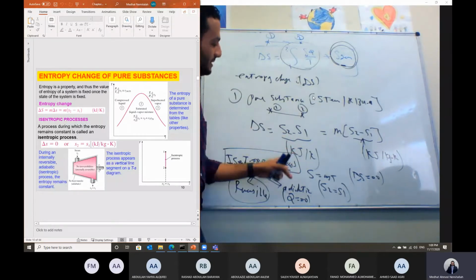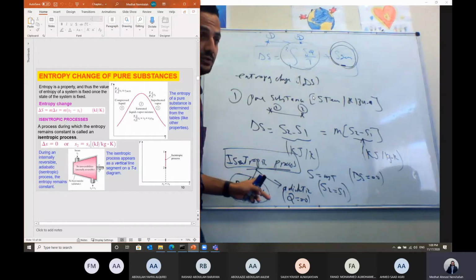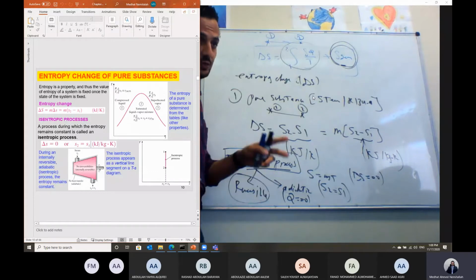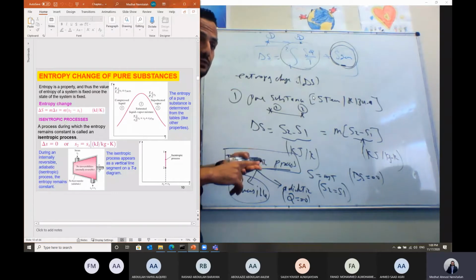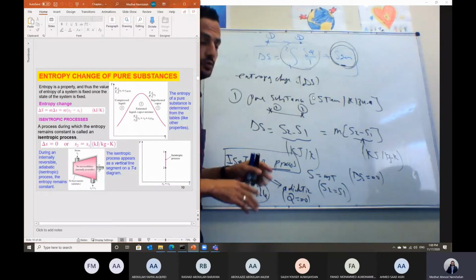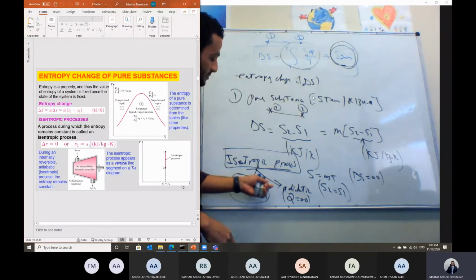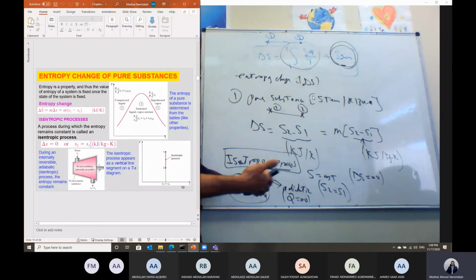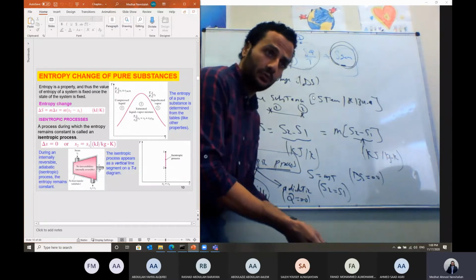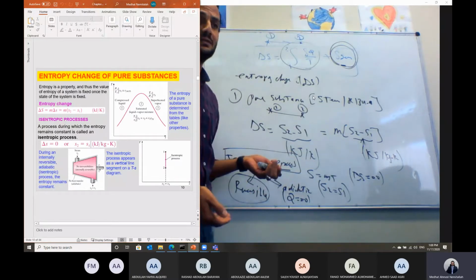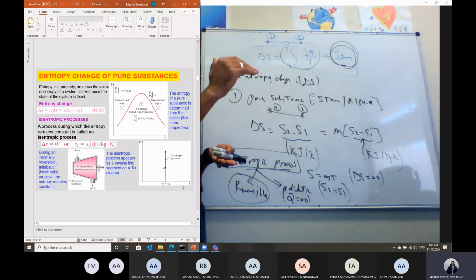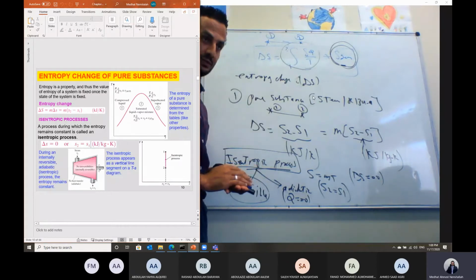But when we assume it is reversible, we cannot have a compressor or any device to be irreversible. But in some cases, we assume the compression or expansion process inside a compressor, turbine, nozzle, diffuser, all of these devices, may be isentropic. Then in this case, we don't have any kind of losses. Then we can calculate the maximum work and compare it to the actual work of this system. This gives us an indication of what we call the isentropic efficiency, which is the ratio between the actual work developed by this turbine divided by the isentropic work in this case.